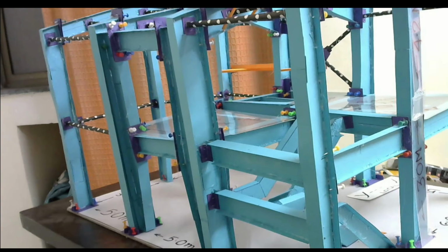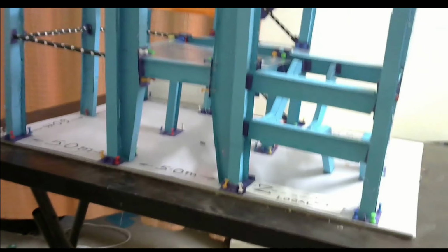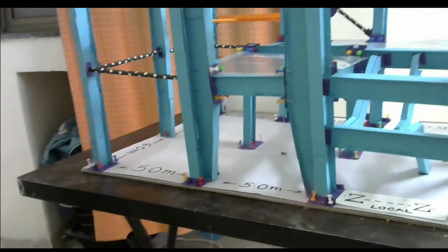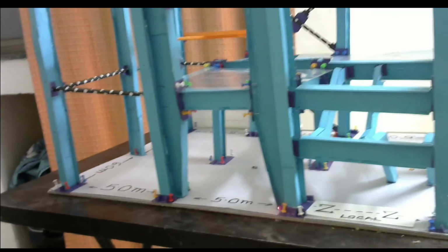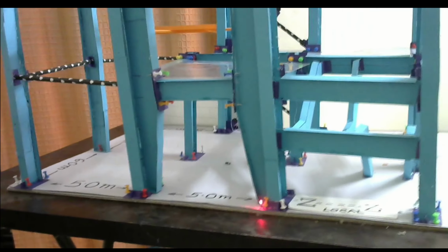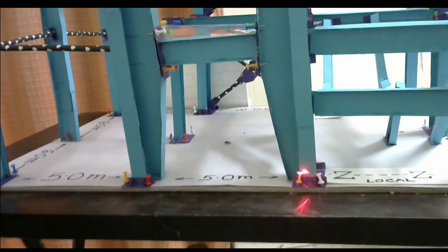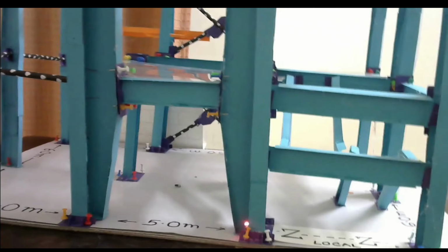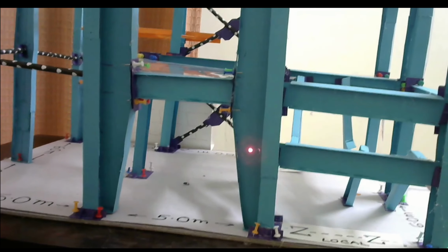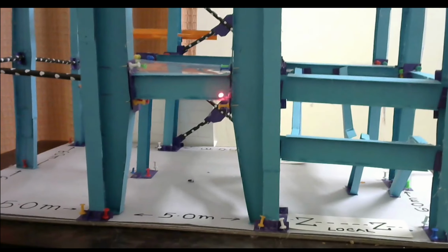Now let us come to this portal frame. This is the portal frame. It is tapered. Sometimes some bolts are provided here, sometimes not. It is simply left as it is on the base plate of the main frame. So this is a pin connection. This is pin at bottom, fixed at top.